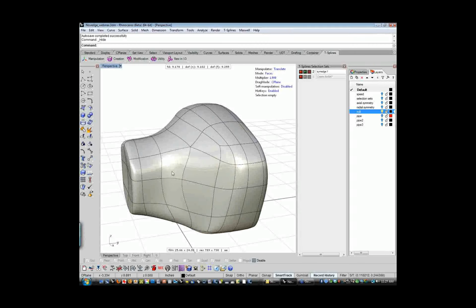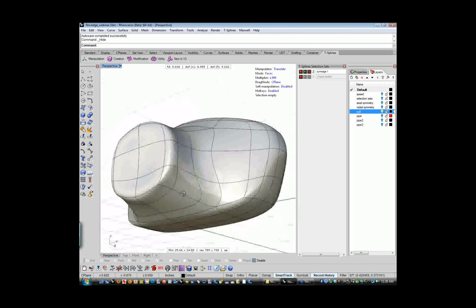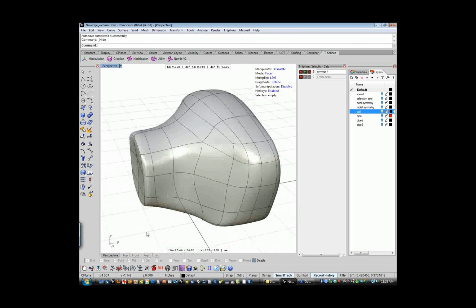Some of the things we're talking about are ways to interactively subdivide the model to let you suck in bits and pieces of the pulled model to more closely resemble the original target model, and ways to make that more useful. But the goal here is to be able to have a T-Splines object and then back form over a bunch of other polysurfaces. Maybe you take a bunch of junk, throw it together in space, and then suck a T-Splines surface over it. Now you've taken these disjointed pieces and created a new single-surface, watertight T-Splines model that you can then edit and modify. So, very cool.